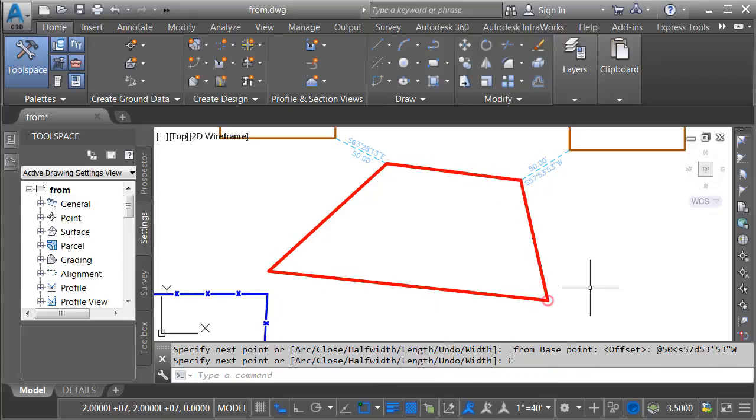As you can see, the object snaps we select don't always have to fall on an object. Using From, we can easily select points that are relative to other object snaps. In many cases, From can also eliminate the amount of construction lines needed to create or edit your geometry.